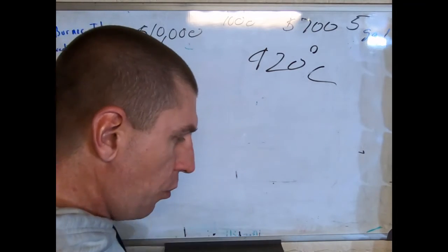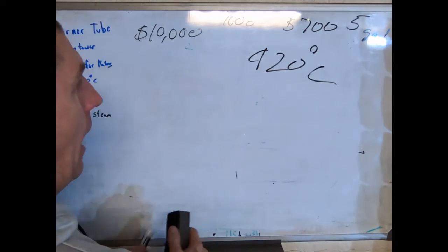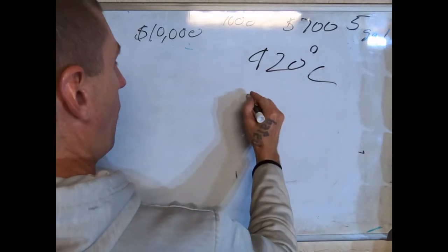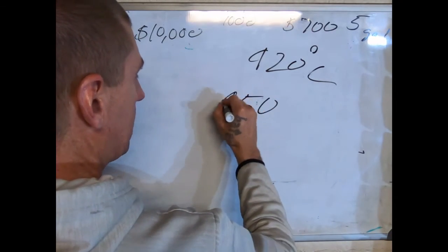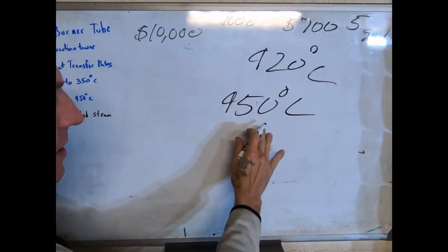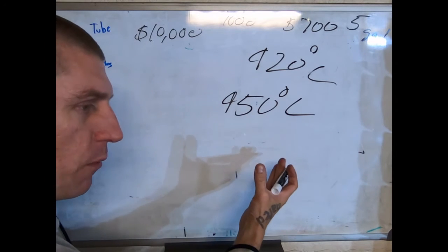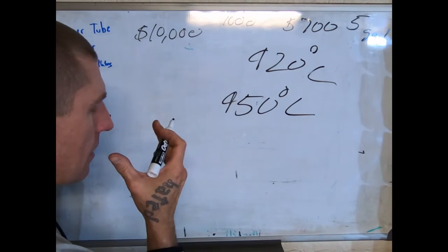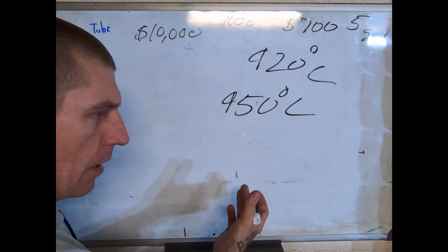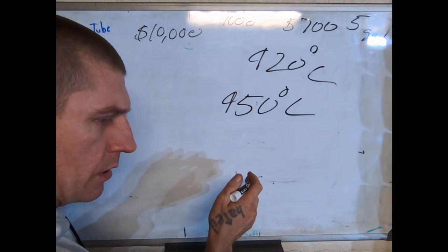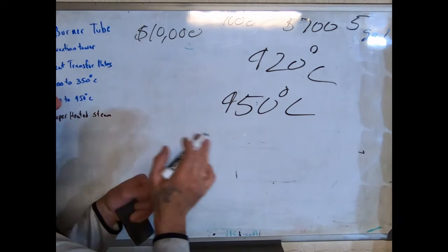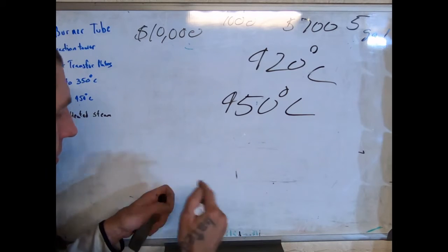But if you guys do want to entertain the idea, I don't like it for the simple fact that 450 Celsius is about the highest temperature for a good thermal fluid that I've seen. Some of them go a little higher. I think I did see one silicone one, but the stuff is just so crazy expensive that it's nuts.